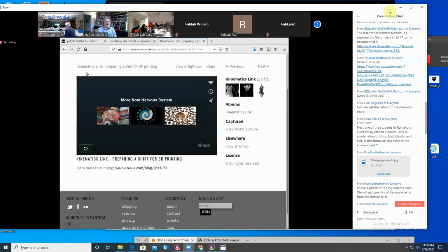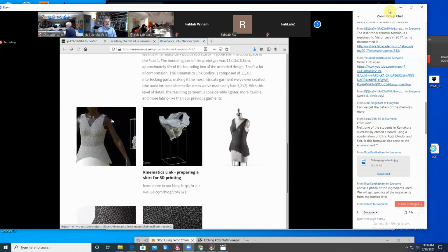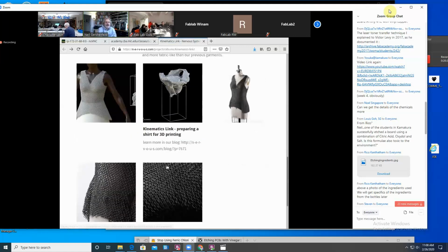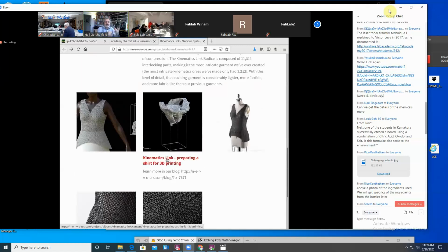When you make it on the laser sinter machine, where the laser fuses it, it's fused. Where it doesn't fuse it, the powder is still there. And so as you're building, the powder kind of automatically supports it. And then when you're done, you just reach in and shake it and pull it out. And you get this beautiful, intricate mesh dress that in other printing processes would be miserable to do, to separate all the support material. But here, the support material is just the powder bed.